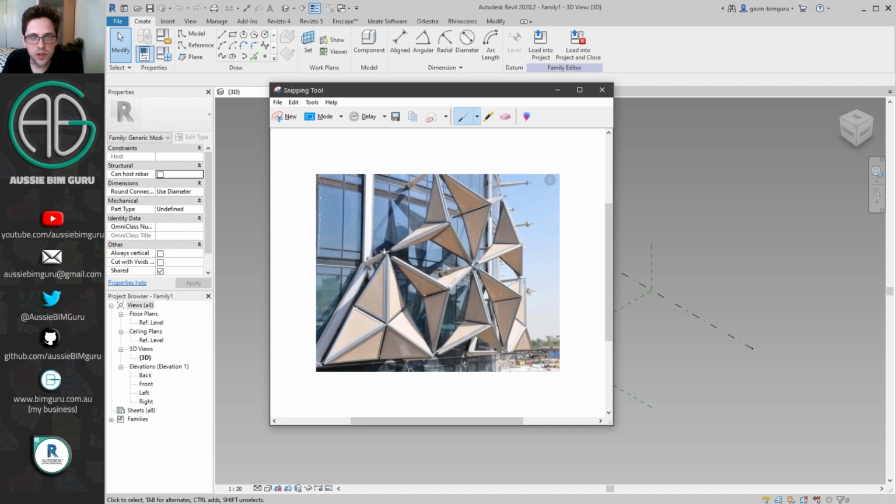In this case, we're also going to have to place a point that moves away from the center, and that's going to dictate the apex of the panel. From there, we constantly have edges back to the main corners, but then we have essentially points that will need to move along these inside edges from the outside edges. And on these 3 points, we're going to place a nested triangular adaptive subcomponent. Now, if none of that made sense to you, that's okay. By the end of this, hopefully you'll be able to follow what we're doing.